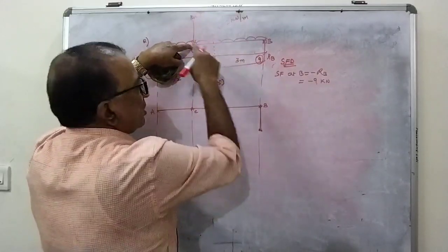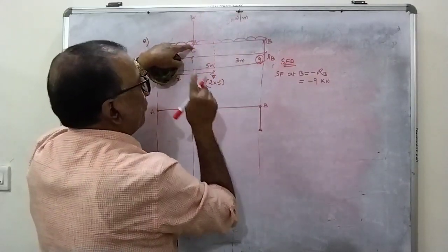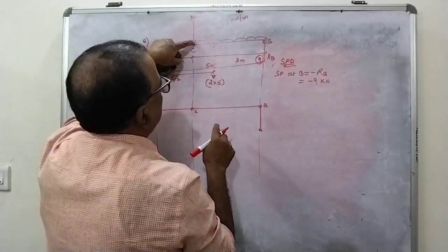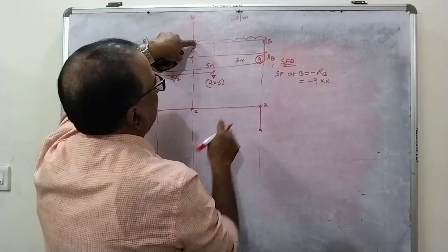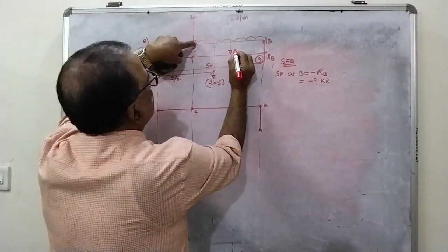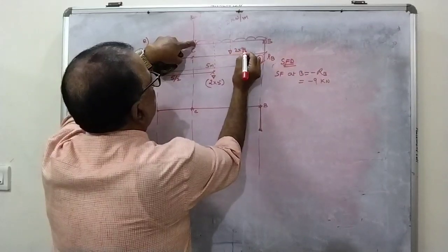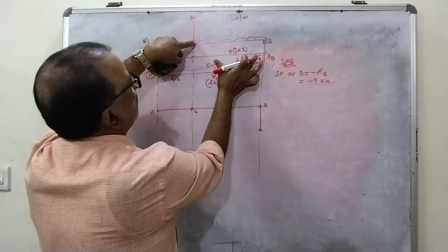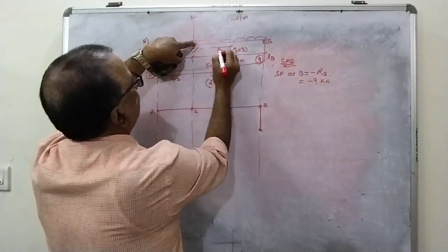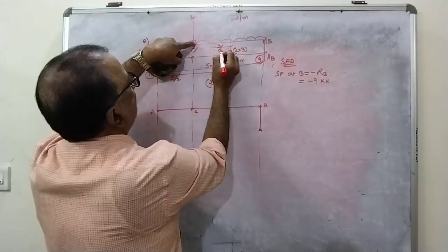Here, it means 2 loads are combining at the C. So for that what you have to do is, already I told you in the cantilever, you calculate just before C. Why? Because this UDL you will be getting. What is this UDL? 2 into 3. Why? Because this is for 3 meters. And at what distance from the C? It will be 3 by 2.